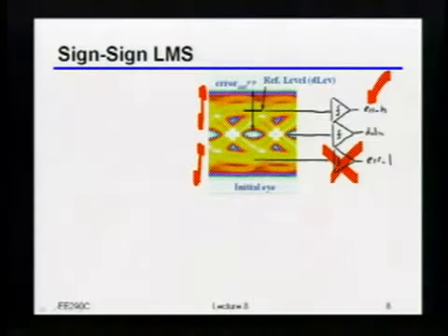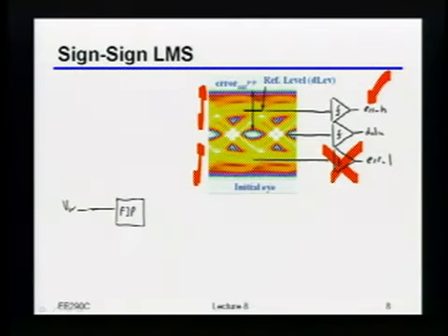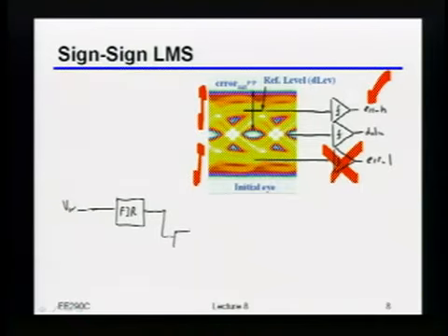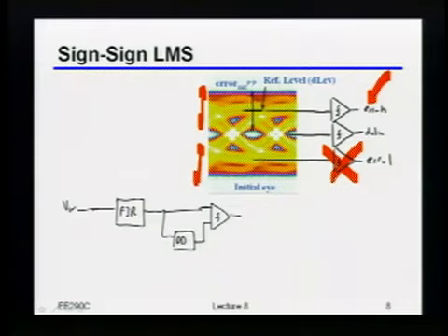Like we did before, like a peak detector. Okay, that's true. You could actually do a peak detector. So I think what you're saying is do something like, take your analog input that is going into, well, I'll just draw it as a block here, that's feeding into your FIR. And then basically do, let's say, a peak detect over here, and then feed that in as the reference for that other comparator. You could indeed do that.